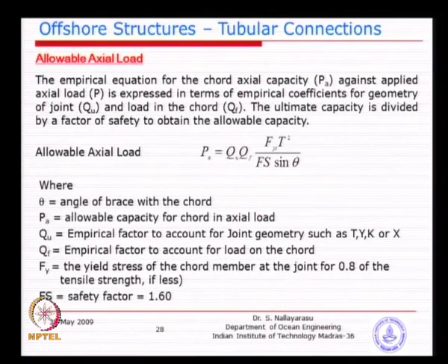In fact, several papers argued that it should be reduced to basically the same as the methodology adopted for tubulars, that means increase the factor of safety to 2.5. But then quite a number of arguments over, then the recent API have adopted, in fact in the previous API the factor of safety was 2.